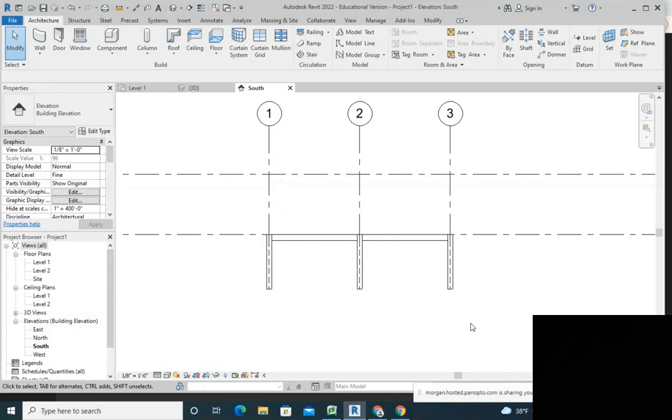Right click on the head. Oh, you can leave that there, it's fine. Yeah, that's fine. So if you click on that, I think it's right click. Yeah, oh, you can bring that up too. That works. Click here. Okay, so zoom into that. If you right click on the head, so click on the head and then right click, and then go to elevation view. Okay, yep, yours are all there. They're just underneath. So you're going to change your detail level here. So change that to fine.